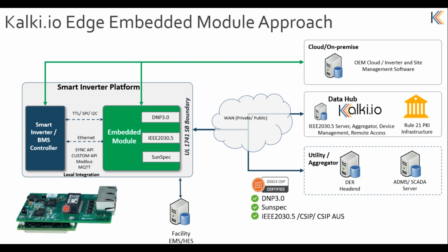And this particular hardware has the stack for DNP3, 2030.5 or SunSpec, which helps you to comply your product with the UL1741 SB or 1547 standard. And all the use cases which you see in the earlier slide can be met.